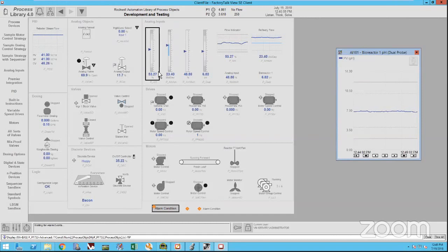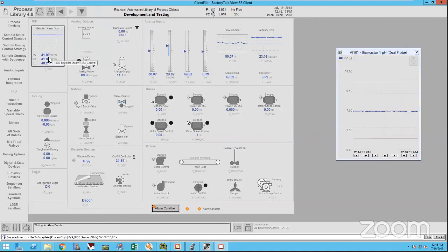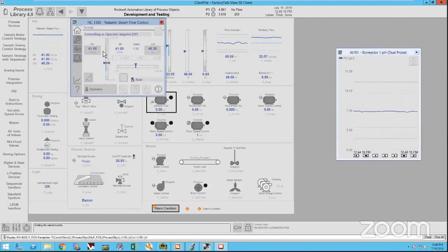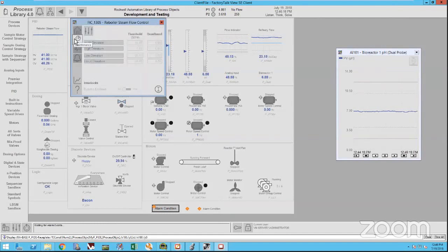There is a shading setting on there so that you can see when something is changing. So over the last 8-hour shift, you can see where your analog has been up and down. All of that's already pre-built into it. You have your PID. So again, this is built into the same topographics, grayscale. As you noticed, everything now went horizontal, where before it used to be a vertical layout. There will be graphics for both SE and ME. So if you're using our PanelView Plus 7s, these graphics are also available for those. The only caveat there is you should be at a 10-inch screen or higher. You don't want to try to put these graphics on a 6-inch. And if you do, just send me a picture so I can see it.